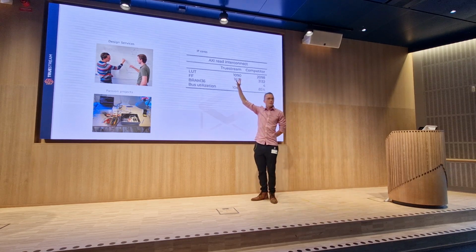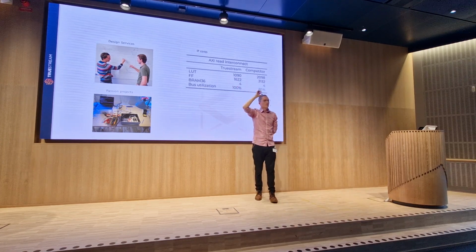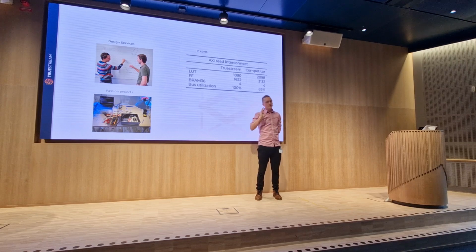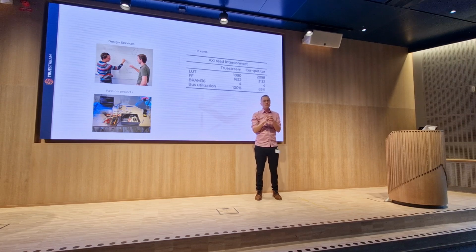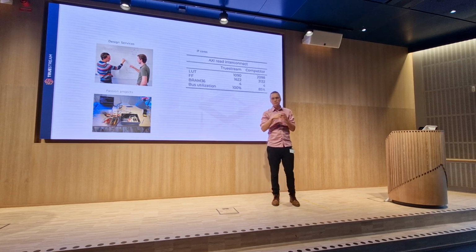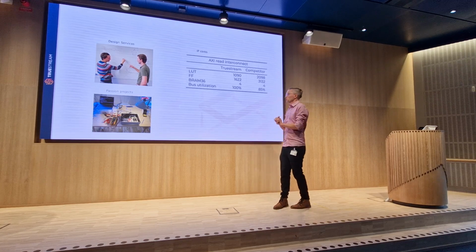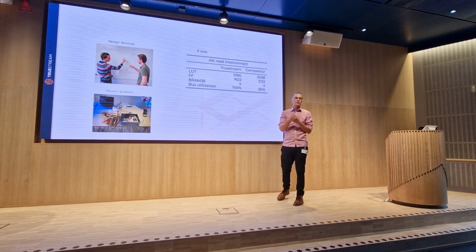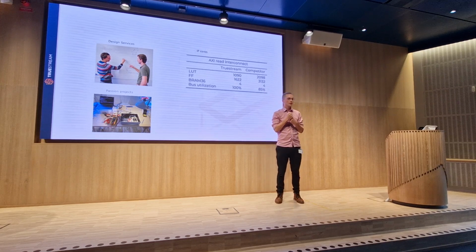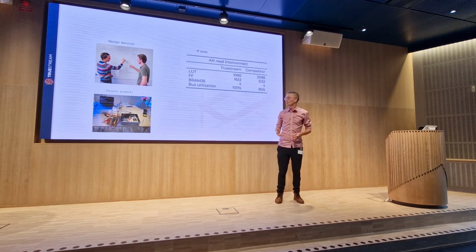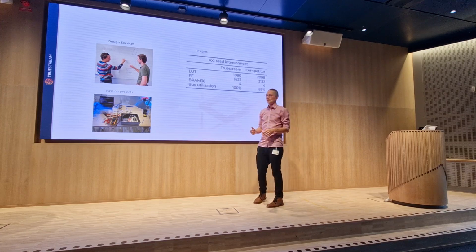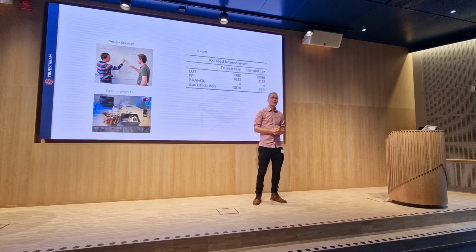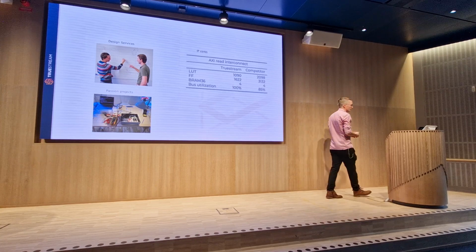And these are actually the reason for this talk. We need to make AXI IP cores and other IP cores that have a really small footprint. So we were using the ones you get for free from the vendor. They are great in many ways. But for one, we wanted it to be simulatable with GHDL, so it needs to be readable code. And we also had to cram more into the device and managed to do that by writing them ourselves.